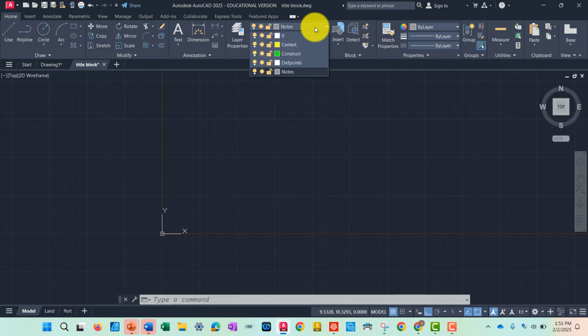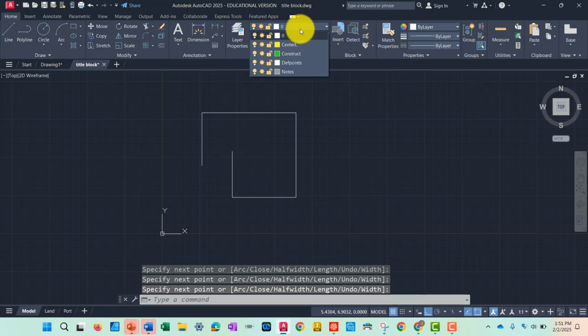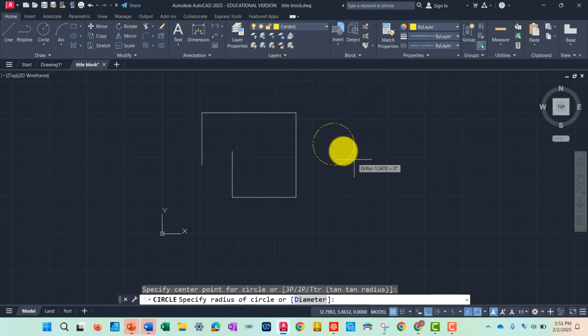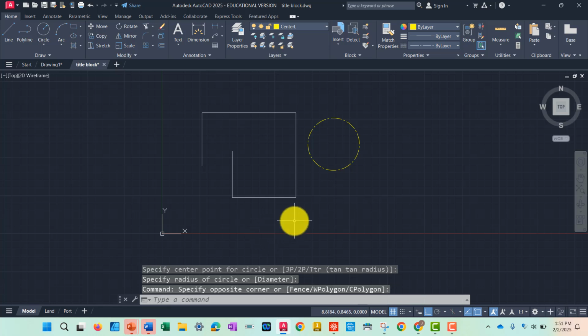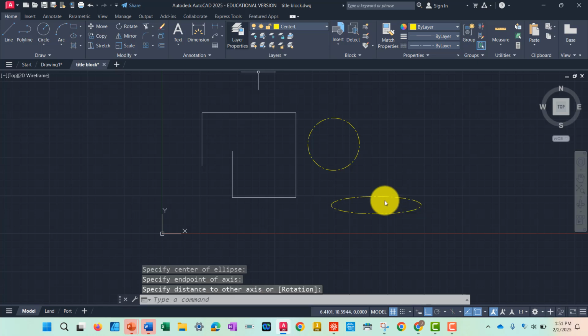And let me show you how the layers work. So if I'm up here at the 0 line, so I select the line in my 2D drawing tools, and if I start drawing something, you can see that is being drawn with a white line. If I come over here and I select something different, so now I have center line up here, and I start a different command, so just see what layer is up here. You can start a different command, and now everything that I draw is going to be in this new layer, right?